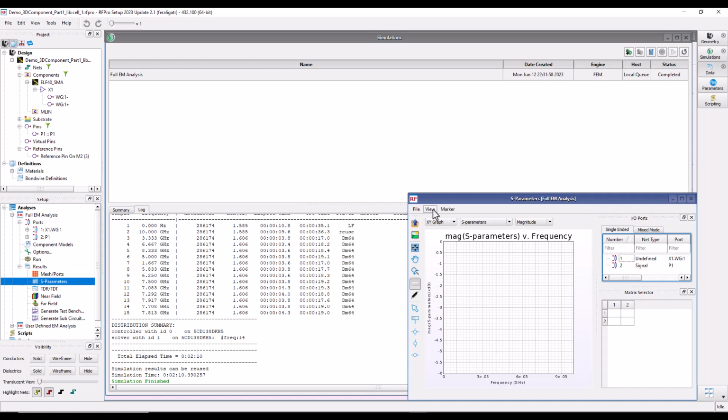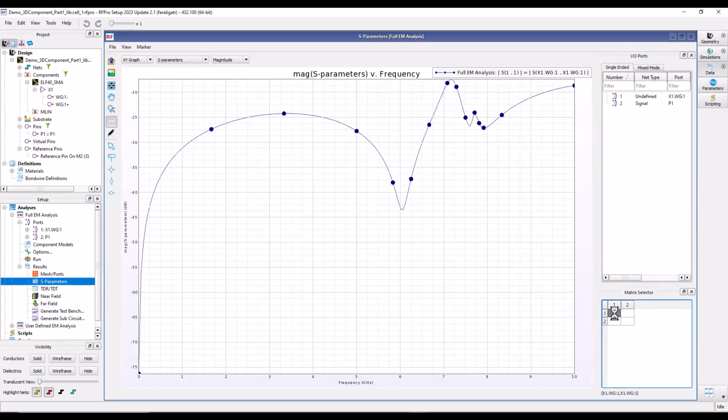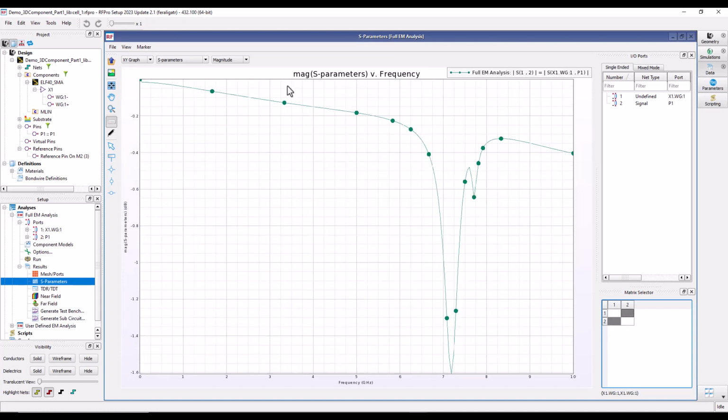And now once we look at the S-parameters of the assembly which we just did in this video, you can see non-optimal performance beyond 7 gigahertz. And again, as I said, I'm not doing a very optimal launch design, but these kinds of effects you can see even in your actual board. So you need to be very careful, and you can see you have caused an undesired resonance, which is not extreme, it is only 1.6 dB, but again, it doesn't look pretty good. It actually looks ugly. So you need to put enough attention on how you are connecting your SMA connector with your RF board, and you have to be careful when you're designing.